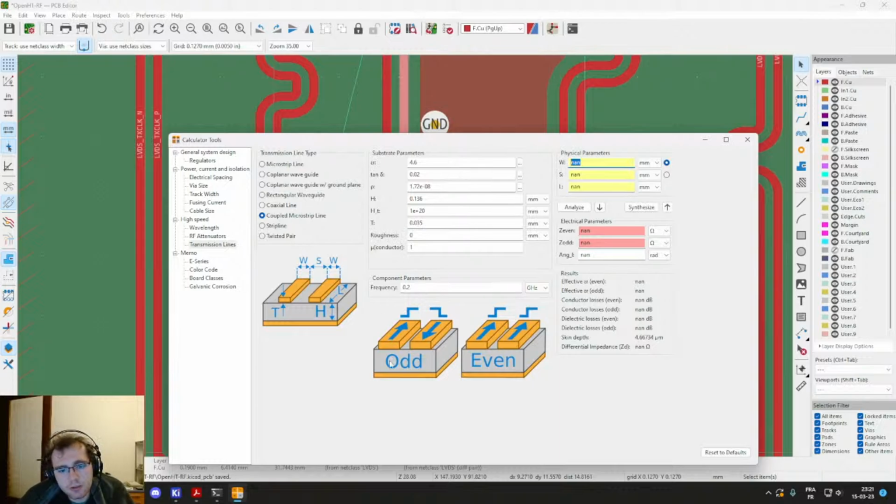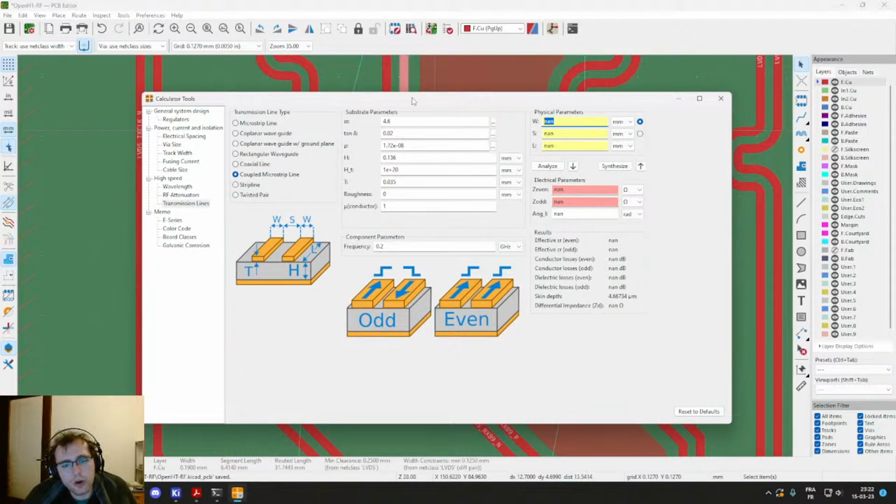Yeah, so basically you take into account all these parameters, because each track of the differential pair is gonna form a capacitor with respect to the ground. And so the impedance of the line is supposed to be 100 ohms, but of course it's not gonna be 100 real resistive ohms. It's the characteristic impedance, which is, if I remember correctly, equal to the square root of the inductance per unit length times the capacitance per unit length.